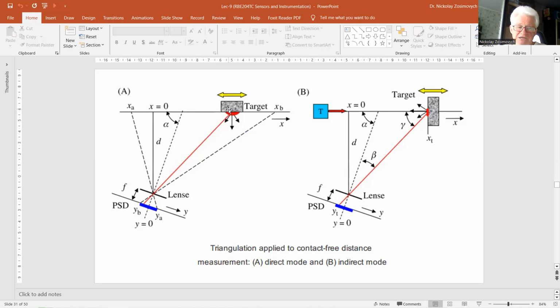It carries an omnidirectional light transmitter viewed by a PSD or a line camera. The sensor is positioned in the focal point of the lens with focal distance f, and this creates a sharp image on a PSD, only if the spot is far away, which in most practical situations is indeed the case.